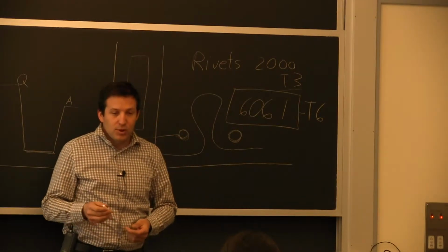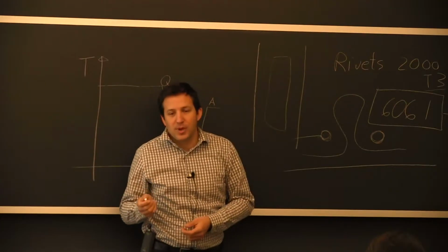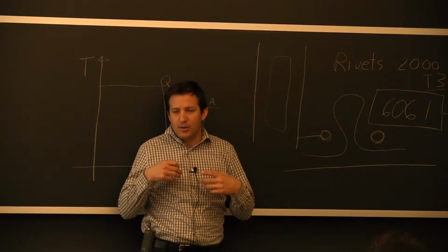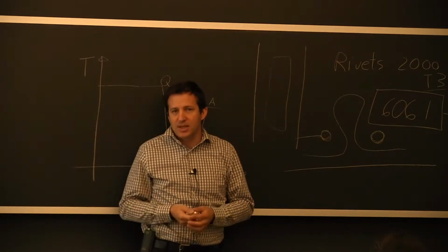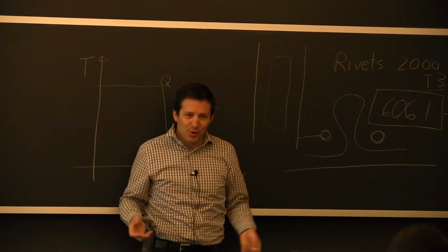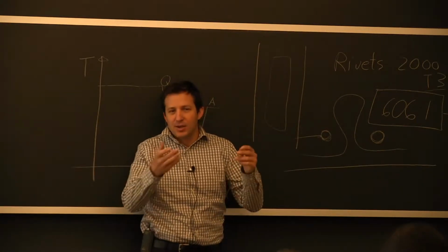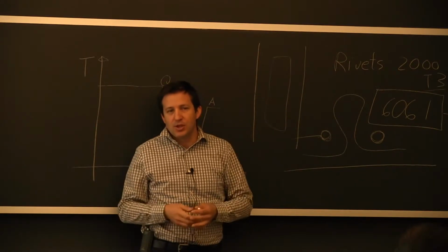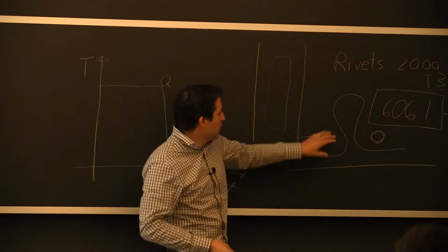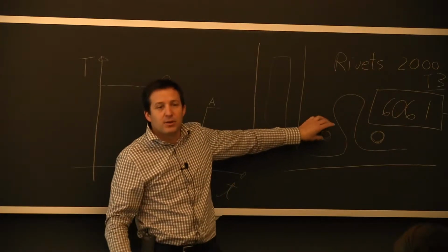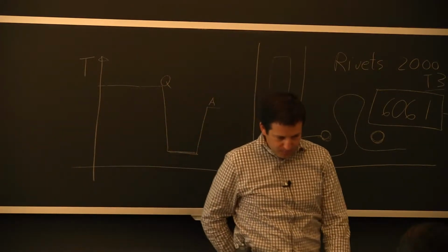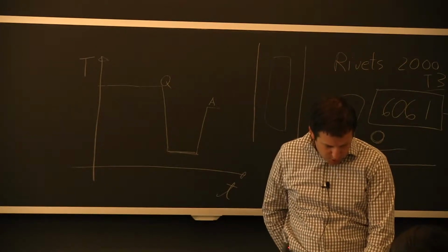We will still use overaged aluminum alloy, especially in the 7000 series, not because of the mechanical performance, but because they have better corrosion resistance. So that always comes into the whole decision-making process where, yeah, you want great properties, but also you need to be resisting pitting if you have chlorides in the environment. And that's what bigger precipitate allows you to do better than if you have a very, very fine distribution of precipitates in the alloy. So that's what I wanted to do for aluminum.